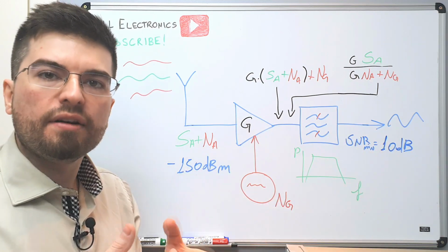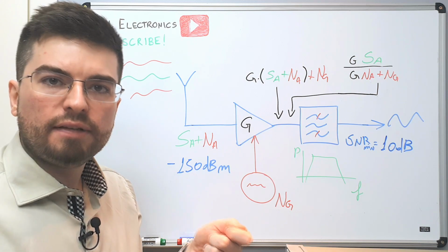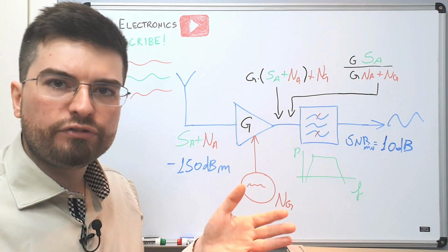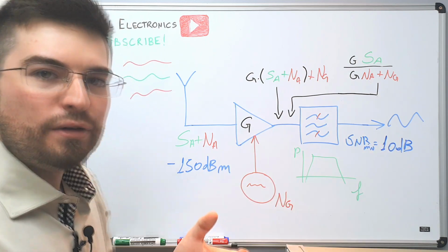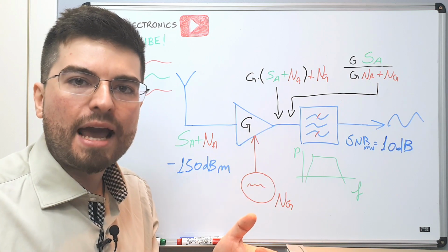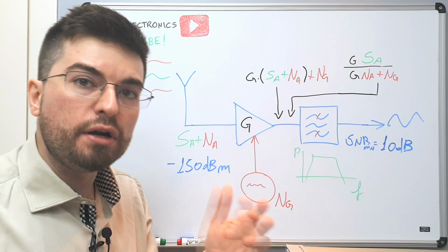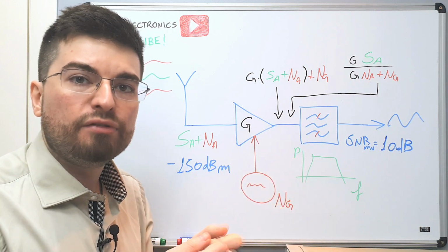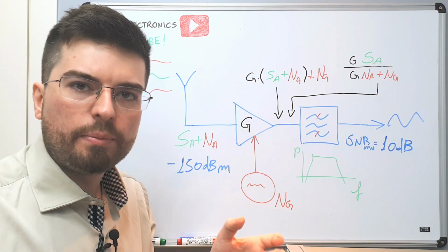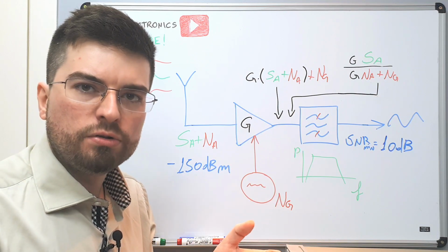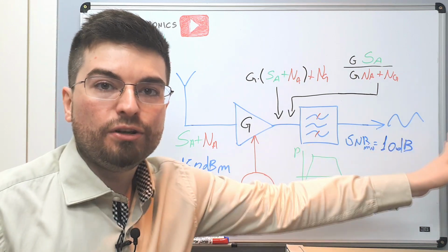For example, we are able to create very powerful error correction techniques that work on very large blocks of data to recover signals with a poor signal to noise ratio, but of course we need more compute time and we're going to add more latency. So actually it's kind of a trade-off. For real-time applications, we cannot create very long and very powerful error correction codes. If it is an offline application, we can have more powerful codes. So it's actually a trade-off for the engineering guys here in the digital world.